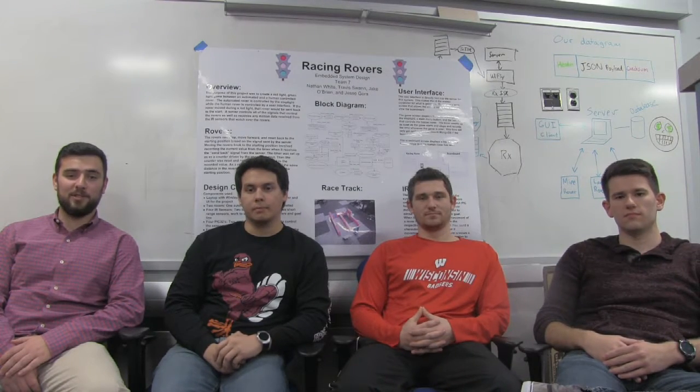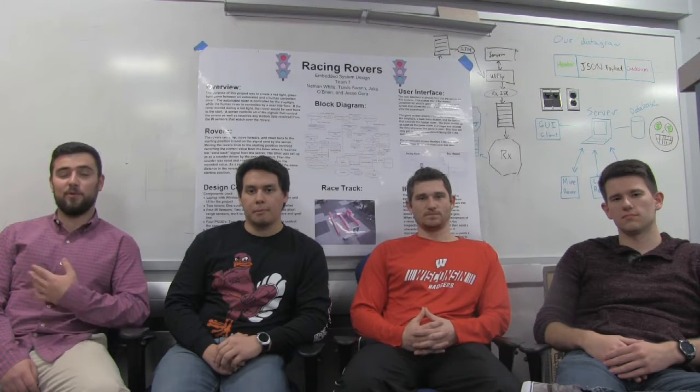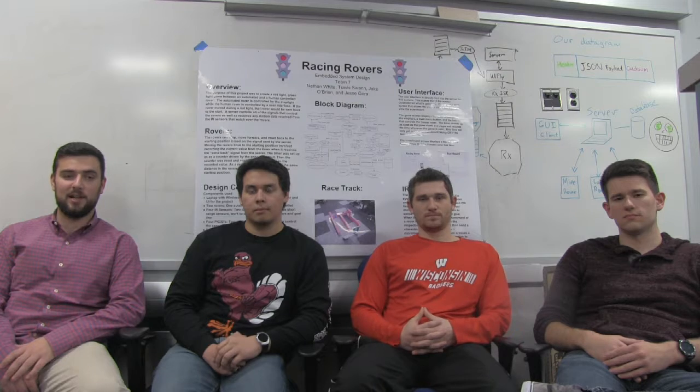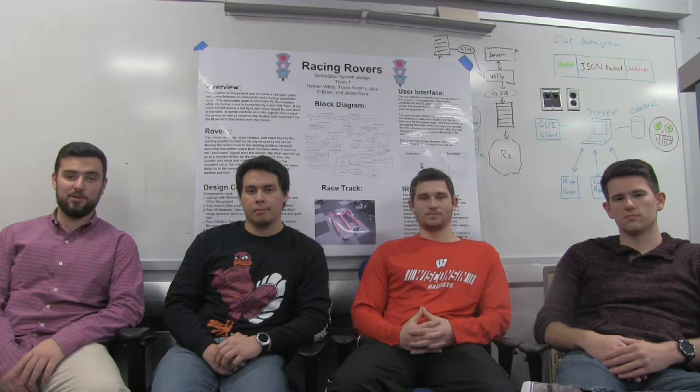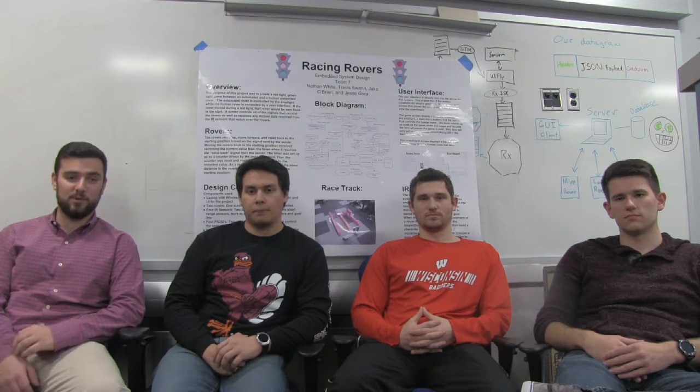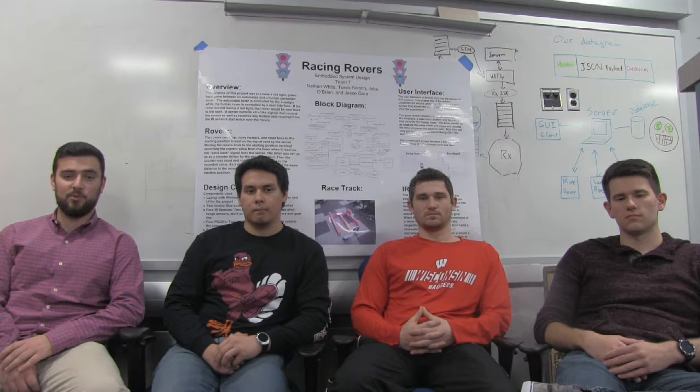So looking back at our project, there's a couple improvements or changes we'd like to make if we had time. For me personally, since I did the IR sensors, I would have spent more time researching different sensors for our project, because the ones that we were using weren't well suited for our task, and it made it very difficult to pick up the rover, especially when it's moving, because the sensors would see behind the rover, bounce off parts of the course, and give a lot of data that we couldn't use, so it made it a lot tougher to sense the rovers when they're moving.